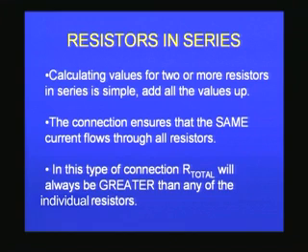Okay, so calculating the value of two or more resistors in series is very simple, because you just have to add them all together. The second point, which I already mentioned to you, is that in this type of connection, the same current flows through all the resistors. This is a second important point.